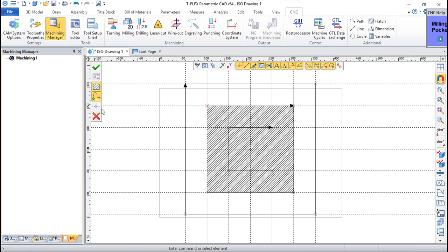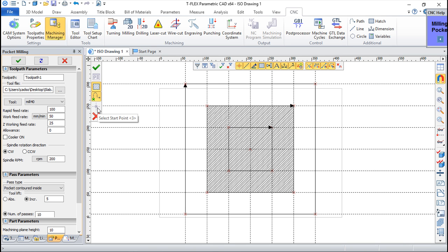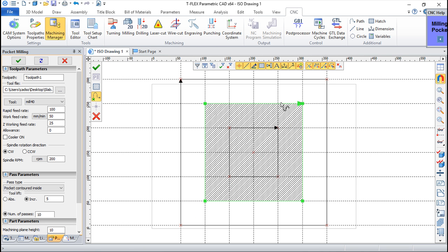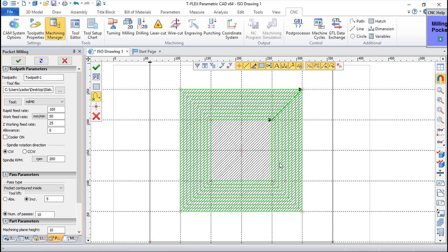Basically, we need to go, let's go again, sorry, pocket milling. We can choose from either edges or simply the paths, so you can turn on or off any of them. Let us leave only the paths. Then we have to choose again a file with the tools, you know this already. And I can choose from two paths. I need to insert two paths, one and second.